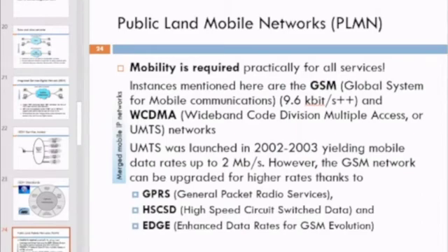The first one is the base station subsystem or radio part, regardless of the technology implemented. The other one is the network switching subsystem, the NSS subsystem, which is basically designed for database and also switching purposes. And the other one is the management system, the network management subsystem. Any technology that has got these subsystems is categorized under PLMN. Therefore, if you have different vendors, different operators and also equipment provided by different vendors, then you can have that many PLMNs. Therefore, the PLMNs throughout the world are numbered in millions.